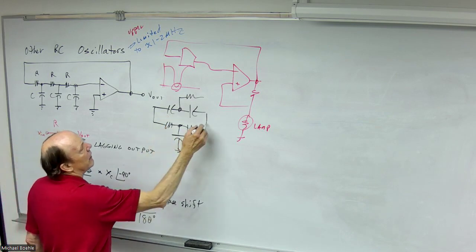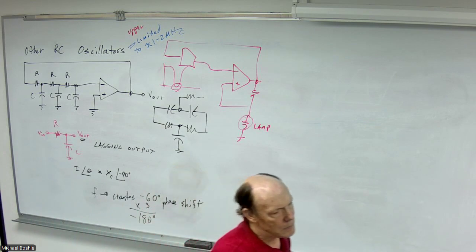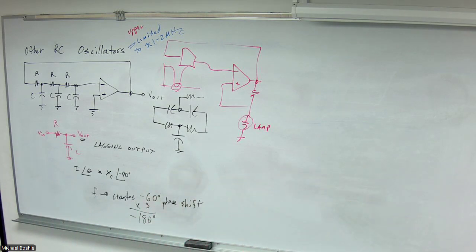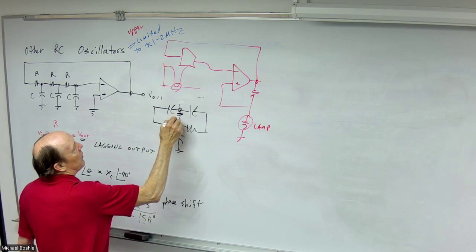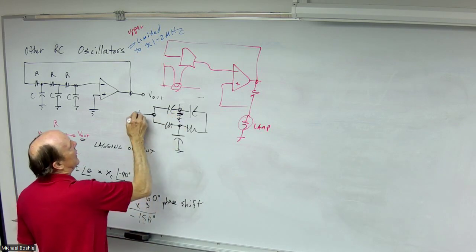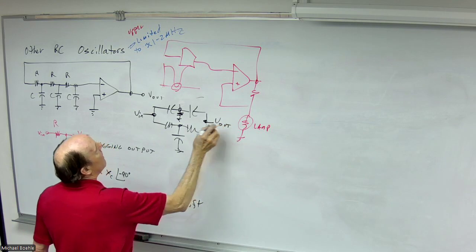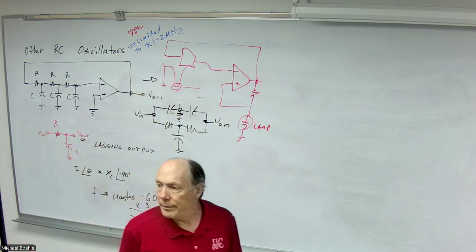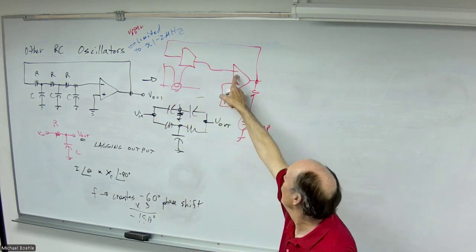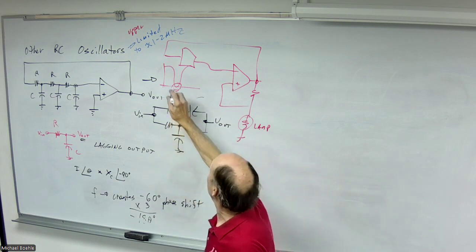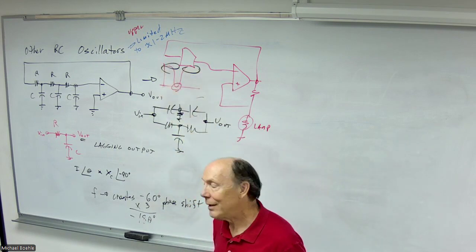So we come in there. I haven't built one of these before. So this is basically V in, and there's V out. And that's the response. So it creates a notch. And so because that's feeding back to the inverting input, I get lots of negative feedback up there, none there.